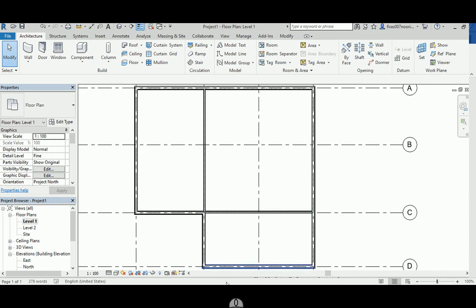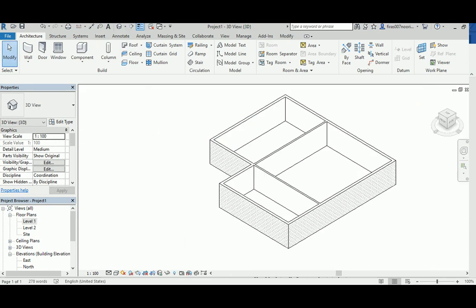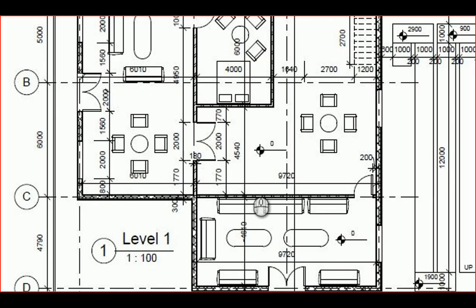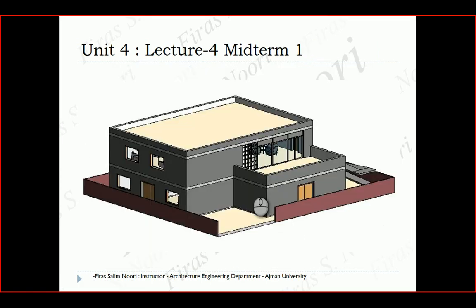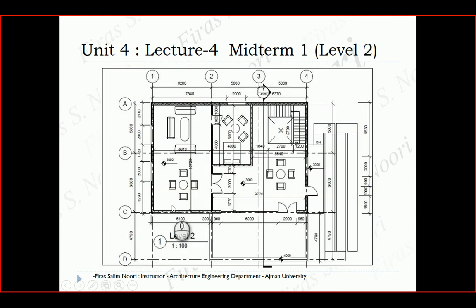Walls. And it's a good idea to go to 3D. That's what we have. And in the presentation here, or in the document provided here, you can see it's working perfectly. Again, it's really a good way to work if you think first about the constructional part and leave the doors and openings and dimensions and the roof to the last phase of the work. So keep going. Don't get distracted by doing windows and doors and furniture and everything else. Just keep the walls and slabs and partitions.